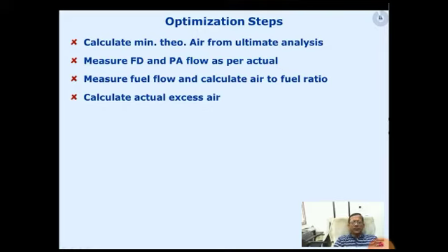Now our optimization process will start with optimizing the 3T's condition, right? So as I told you, the first approach is we want to have an optimum SA to PA ratio. So what we do, we start reducing the PA, but it has to be done by a small margin, not just reduce it with a large amount, just reduce it by a small margin.